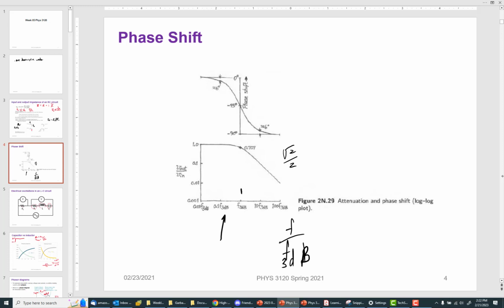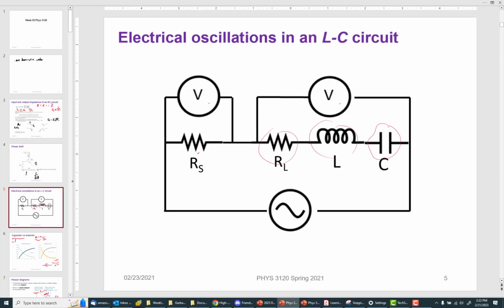There's a 50 ohm form, there's a 75 ohm form, that's the one that TV cable uses because of the frequency that goes across for TV signal, cable TV. 50 ohm is the best general purpose, but we need to learn a lot more, and it's something that I understand deeply that I couldn't explain it right off the top of my head, but we'll get there.